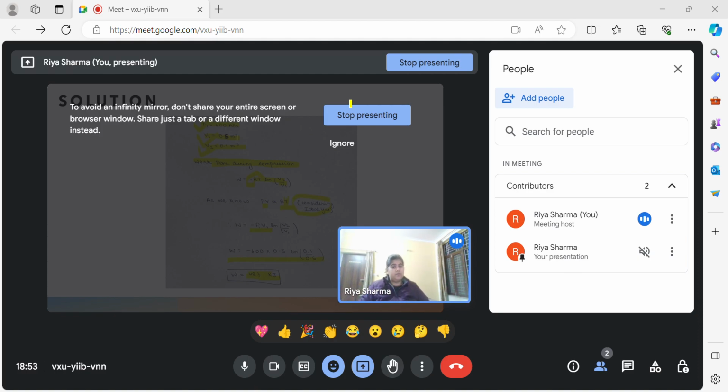And as we know, PV is directly proportional to RT. Considering an ideal gas, work will equal minus P1 V1 ln V2 by V1. V1 is equal to 0.5. Put these values in, try to do it by calculator. I have done a similar question very easily, showing how you should write it so that you can secure optimum marks also. Spend 2 minutes understanding the question and write the given values.